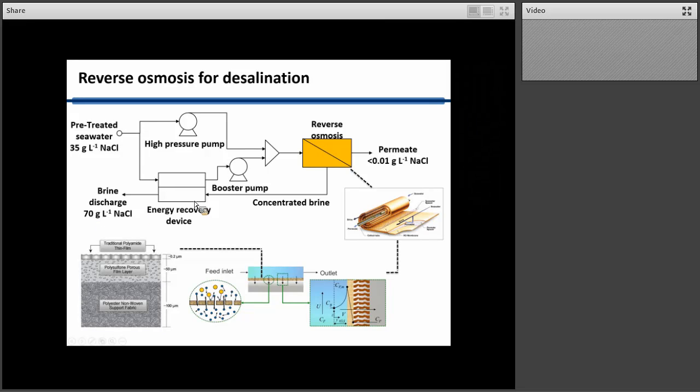And of course, to do that, I use one of these spiral wound membrane modules, and that spiral wound membrane module is made up of a whole lot of leaves rolled around a permeate tube. If you look at the level of the individual membrane, there'll typically be a layer near the surface of the membrane where there's concentration gradients because the water is passing through the membrane. We call that concentration polarization. And at the very separating layer of the membrane, what you've got is water passing through and salts hopefully being rejected from the membrane. As I alluded to, this is a thin film composite, so we'll have a non-woven material that we use to cast an open membrane on using phase inversion, and then a traditional polyamide thin film.